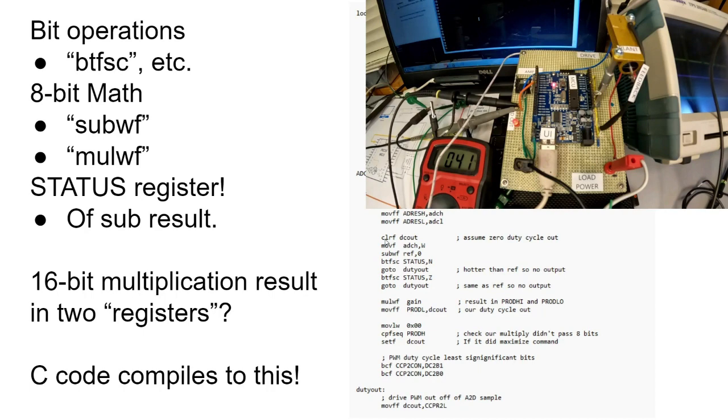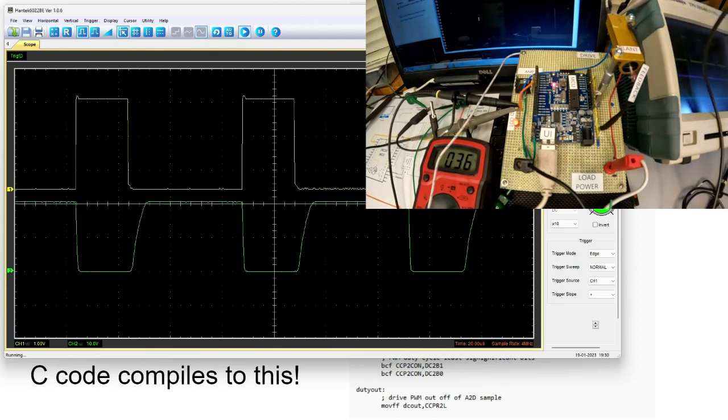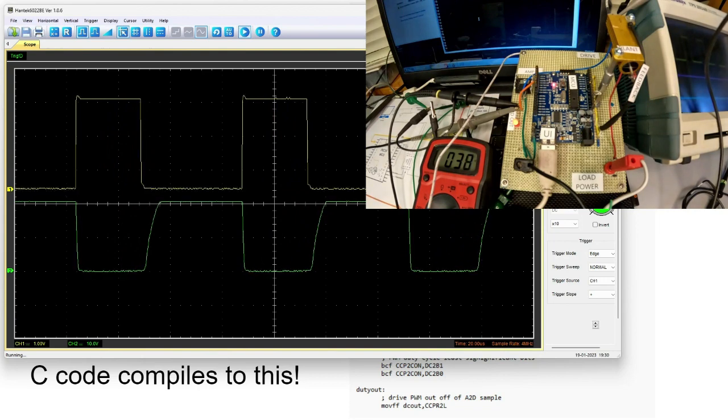So now we are coming back down, and we had our fan running, and we can see on our meter that we're regulating back at 41 degrees C. Again we're triggering on the scope, which means we cooled down, and we have again entered this region. We'll look at the scope. I'll put a little real cold on here, and you can see that pulse go up, and then we'll bring it back.